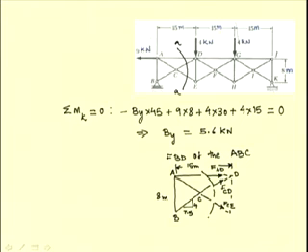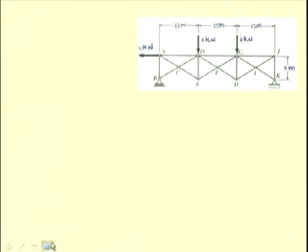And since we have seen that the forces are concurrent, like the forces FAD and FCD are concurrent at D, and these two forces are concurrent at C, and these two forces are concurrent at A, it is convenient to consider the moment equations. So, the first equation that we write is the summation of the moments about A. For your convenience, we have considered this section AA.